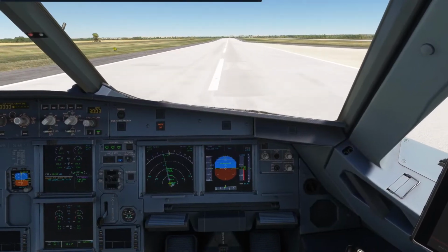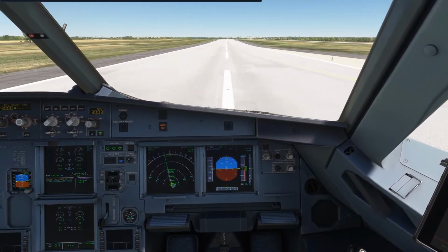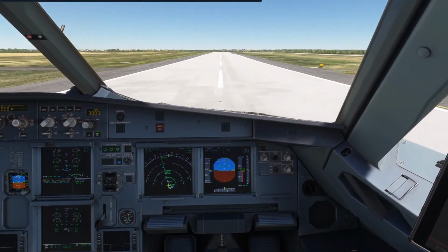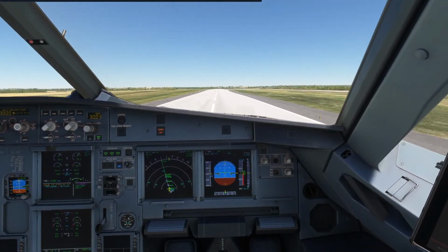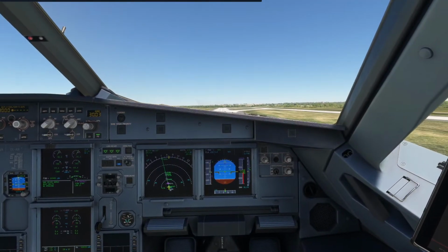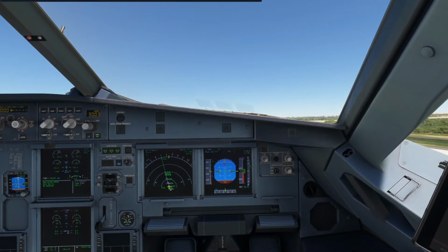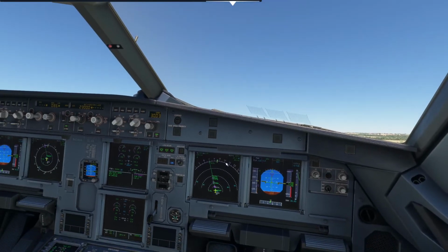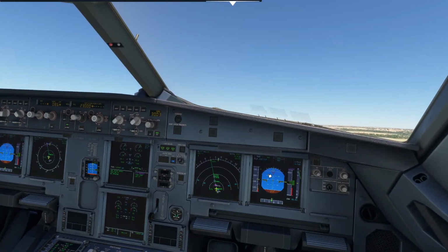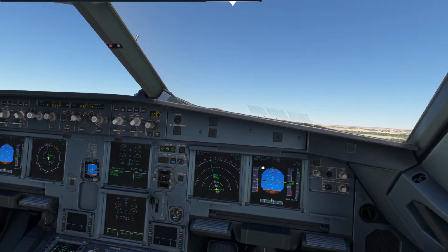And that 1 indicates V1. Your hands come off the thrust levers. There's V1. Rotate. We'll go ahead and rotate about 3 degrees a second. And for some reason, there it is. Follow the SRS, which is the flight director. Positive rate of climb, gear up.